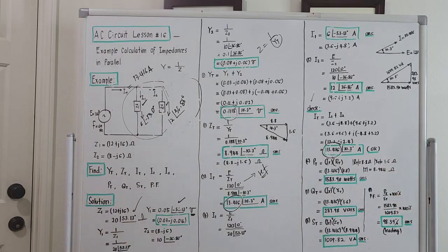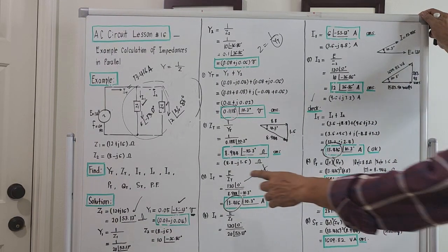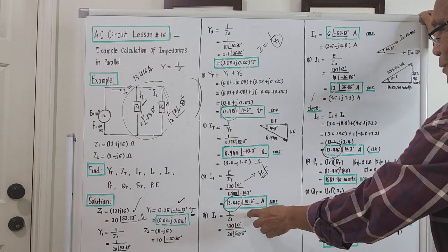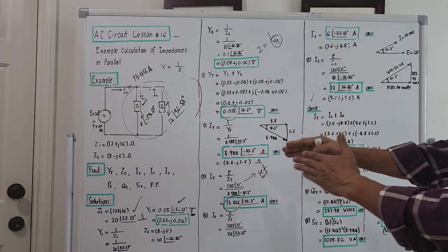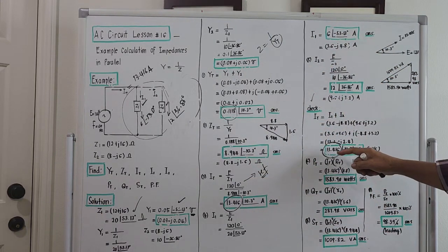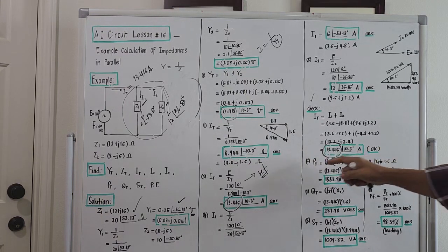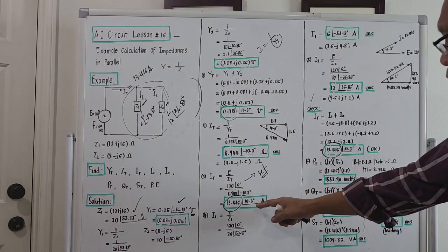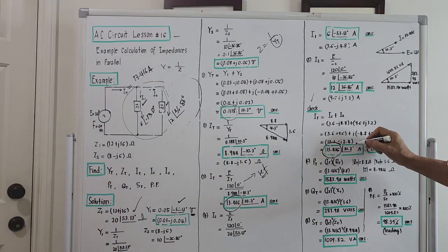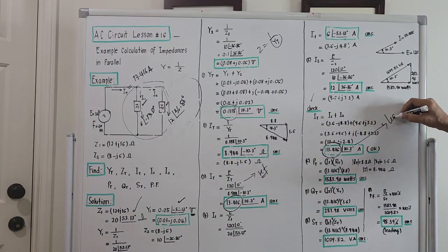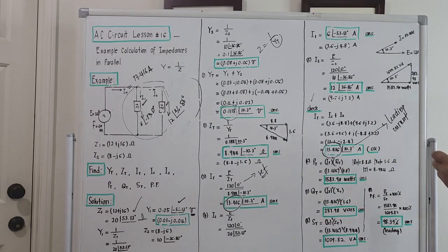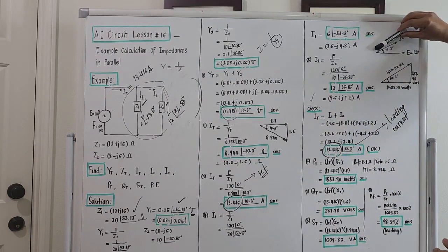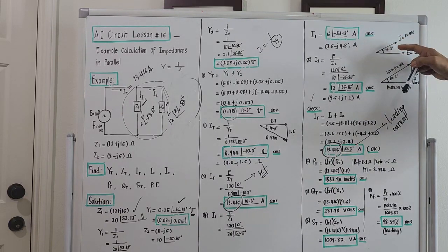So by bringing out two solutions, I total by the direct solution is 13.416, and by taking the sum of I1 and I2, what comes out still for the value of I total is 13.416. The angle is 10.3 degrees, amperes. The angle here is plus, meaning this is a leading current. The power factor is leading. This is the applied voltage, and this is the current, and the angle between them is 10.3 degrees.